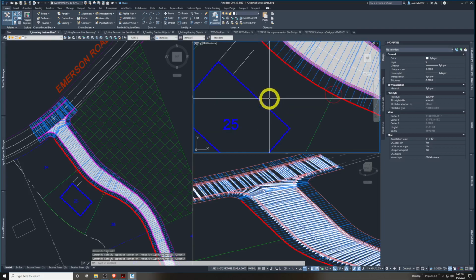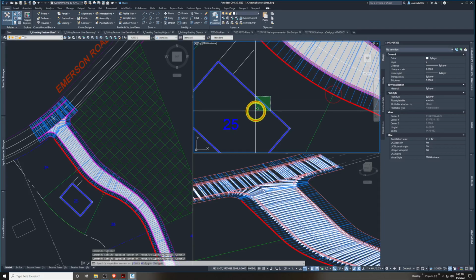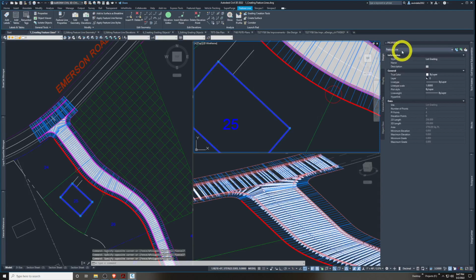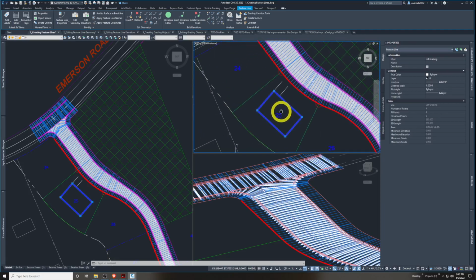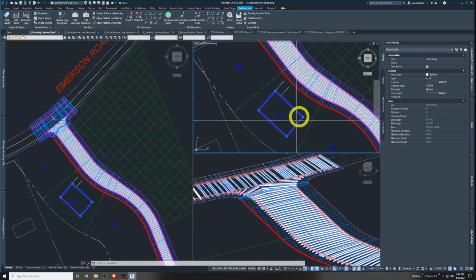And if I hover crossbox in the negative direction this way, I just have one feature line. So if I would have not selected erase existing entities, I'd have a feature line and a polyline there. And it's located at elevation 0. So if I hover on these like this, pay attention to down here. So watch this as I go up here and hover.